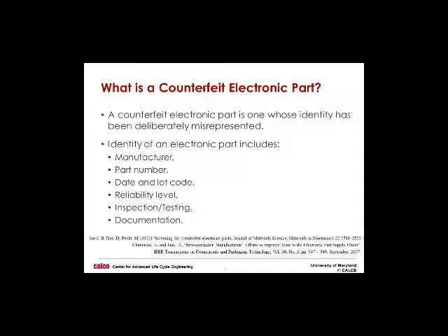Let me quickly define what is a counterfeit electronic part, and this is actually not the same as what you might see in many standards. All I'm saying here is I look at a counterfeit part as a component engineer, not as a lawyer, not as an investigator. So I want to just make sure that I'm getting the part that I need for my product. So from that point of view, an identity misrepresentation of an electronic part that may create a problem for me would be if the manufacturer, part number, lot code, reliability level, or even the documentation is presented incorrectly.